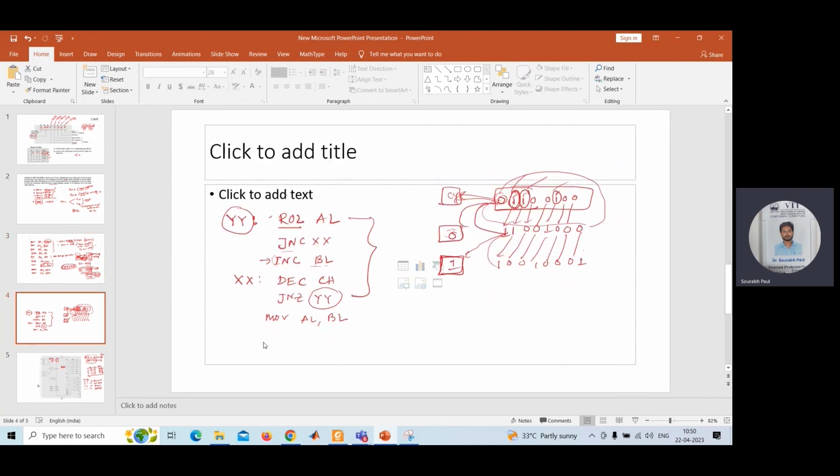So in the programming also, what you need to do? Add DX, 04, which means you come to the address of port C. Whatever BL value you got, meaning how many LEDs are on, that number you need to show in port C.